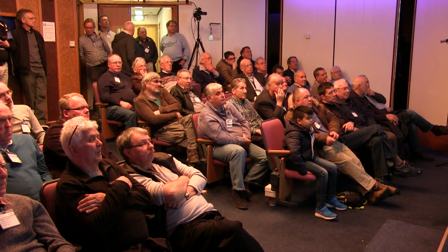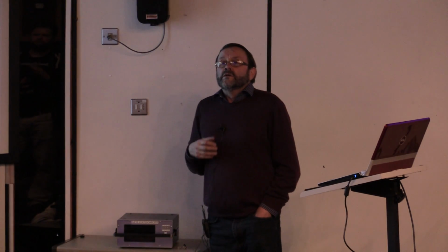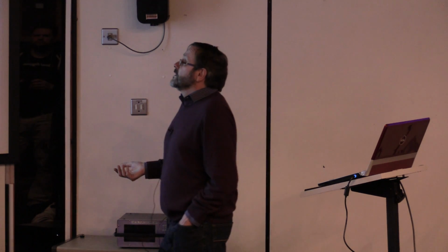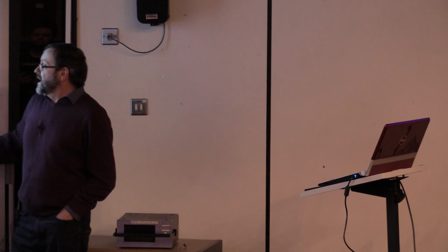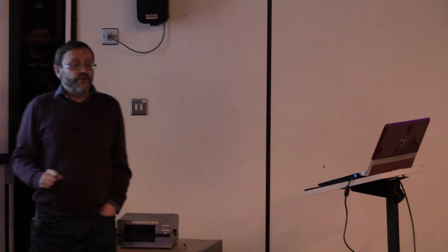If you're prepared to have a little less signal to noise ratio than the beacon but still be decoded, so rather than the numbers we've used here, which was for 8 dB MER, but you drop to 5 dB MER, you can reduce your relative power again. So the numbers we're coming out with here are for 125 kilosymbols at 5 dB MER. You could probably run 7.5 watts into a 1.2 meter dish.